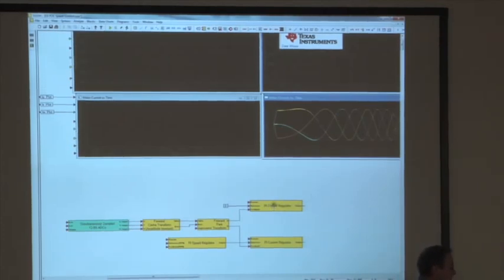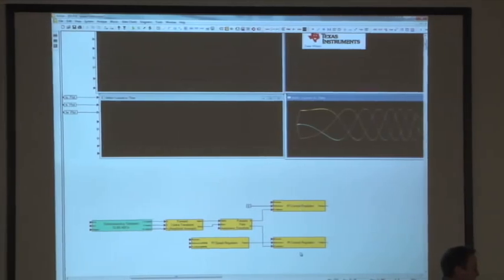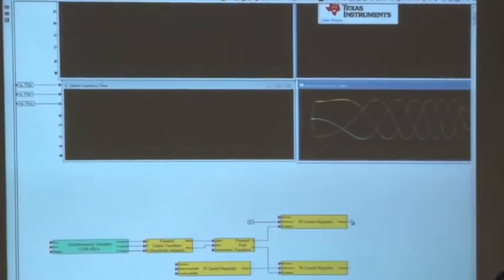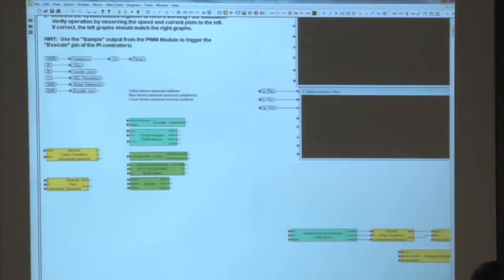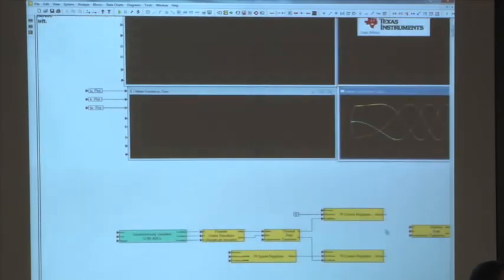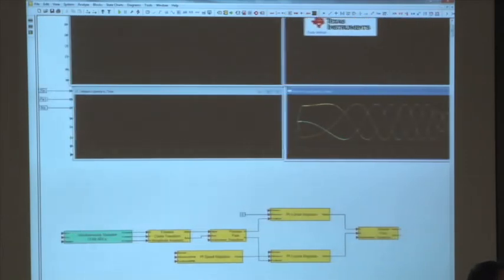We've got our PI current regulators for the D and Q axis. They are generating correction voltages, VD and VQ. Once we have those, what do we want to do with those? Inverse what? Park. All right, let's go grab the reverse Park. And we'll feed that into, see the top one, we'll just connect its output right into D. And the bottom one, we'll put its output into Q. And once again, we need angle information, which we don't have yet. So we'll wait for that.